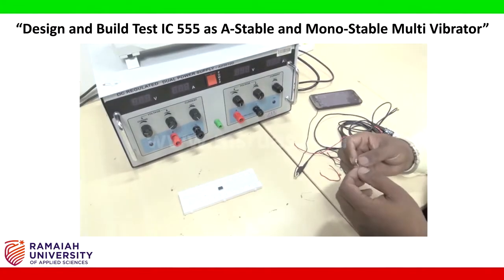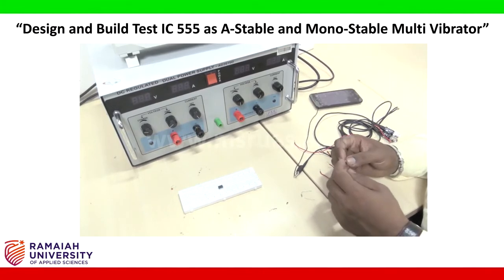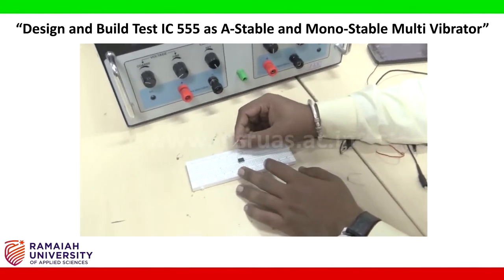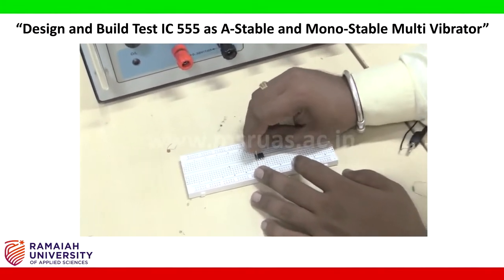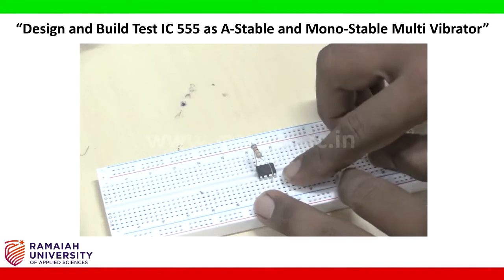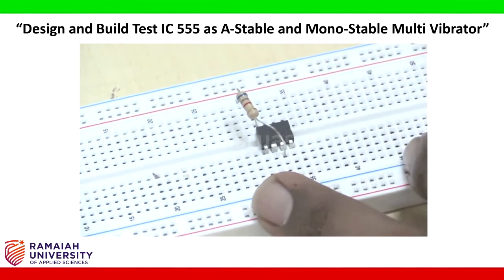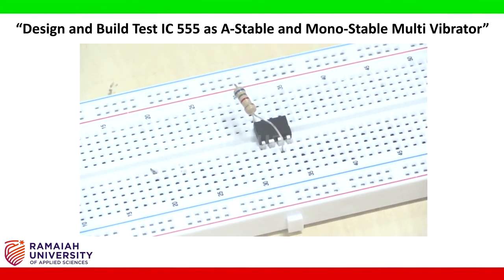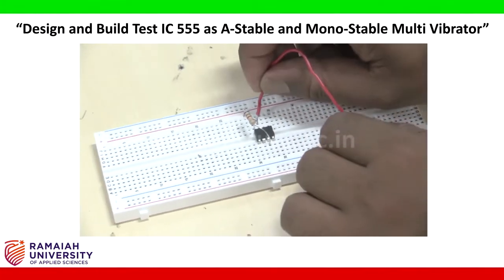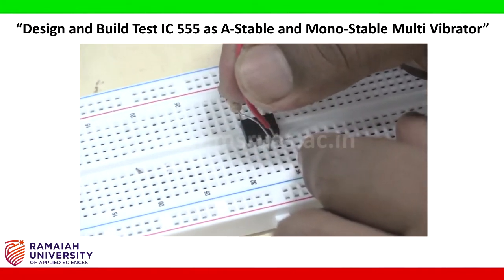I am taking a 7.2 kilo ohm resistor and I placed that 7.2 kilo ohm resistor in between terminal 4 and terminal 7. This is terminal 4 and this is terminal 7. I placed this 7.2 kilo ohm in between terminal 4 and terminal 7, and I want to make terminal 4 and terminal 8 a short. So this is terminal 4 and this is terminal 8, I made it a short.